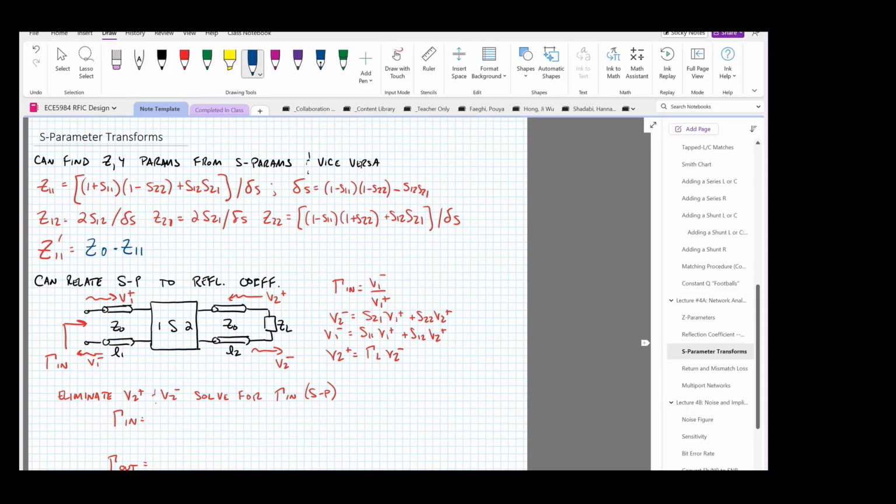And 50 ohms was a good compromise between maximum power transfer and minimum loss in a cable. And so we are stuck with it today because of that. Nowadays we can make a transmission line with any impedance that we want, practically. But when you get a legacy investment in infrastructure, it takes a long time to get rid of that. So 50 ohms is our choice.